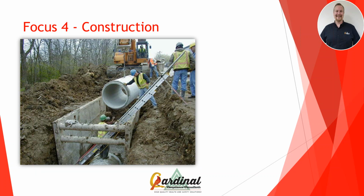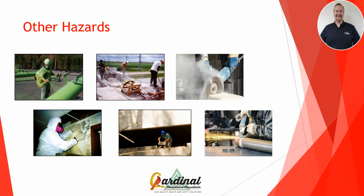And that's just out of the focus. There are other things that I'm sure you saw wrong with this picture. You'll notice on the left side of that trench box, that soil is placed all the way to the top of that trench box. Now, we need to have about 18 inches of the soil level beneath the top of that trench box. But again, there are several examples of accidents waiting to happen. And these are accidents that could change somebody's life forever if it doesn't take their life.